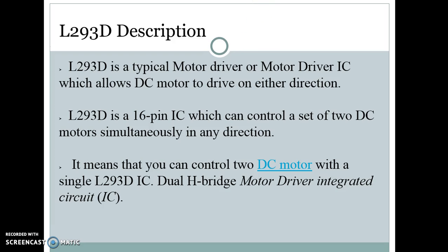Let me tell you about L293D motor driver IC. L293D motor driver IC acts as an amplifier to drive the motor. If we connect the motor directly to the controller, then the current is not sufficient for the motor.